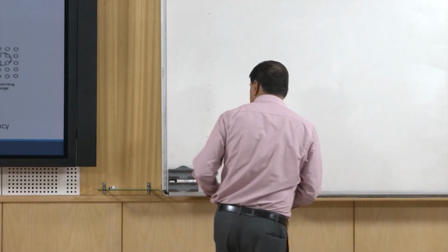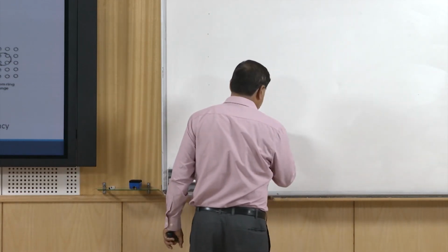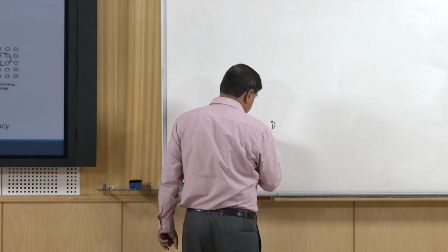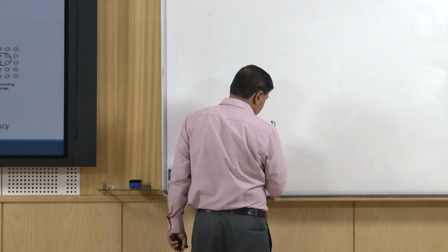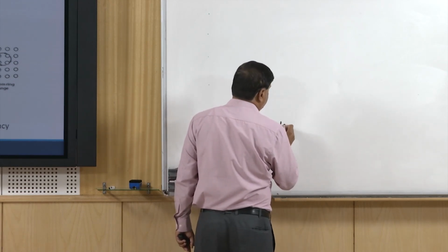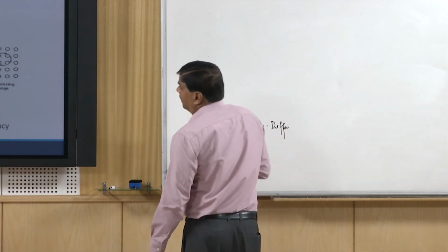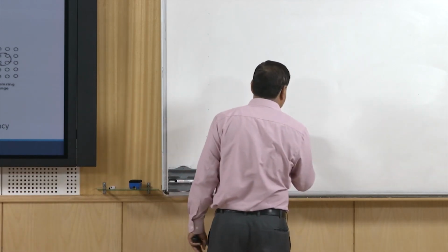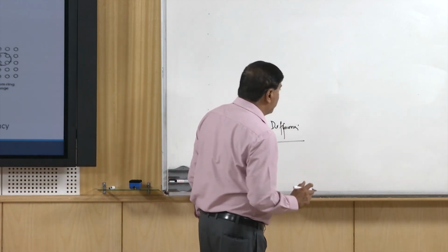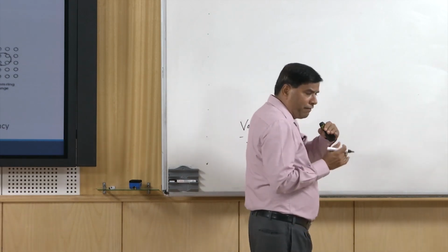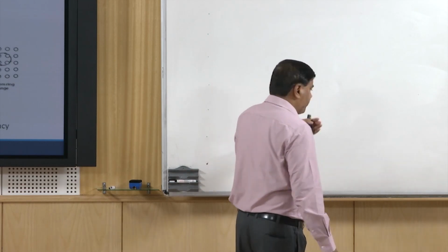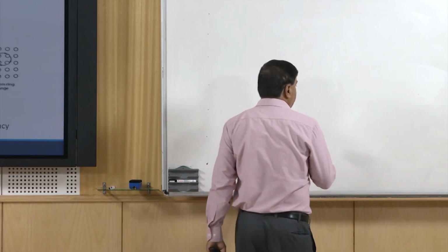If we see these, the vacancy diffusion needs the minimum activation energy, while the exchange diffusion requires the maximum one. So, to exploit this aspect, efforts are mostly made to have more vacancies near the mating surfaces, so that the diffusion across the interface can be really facilitated.